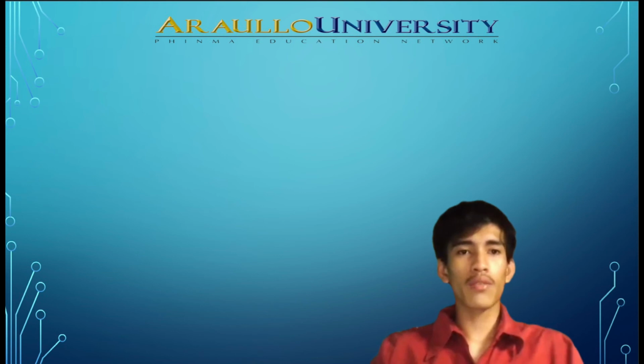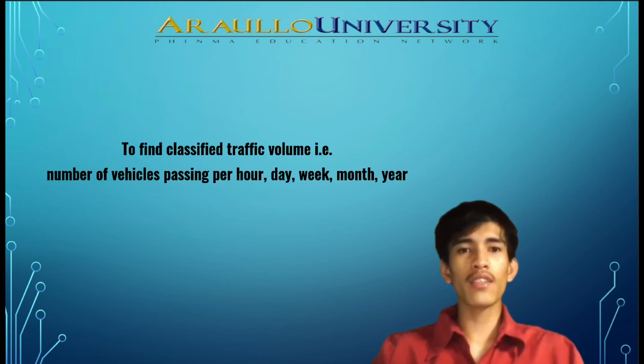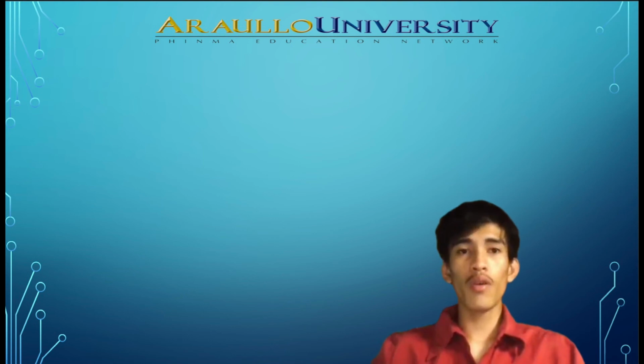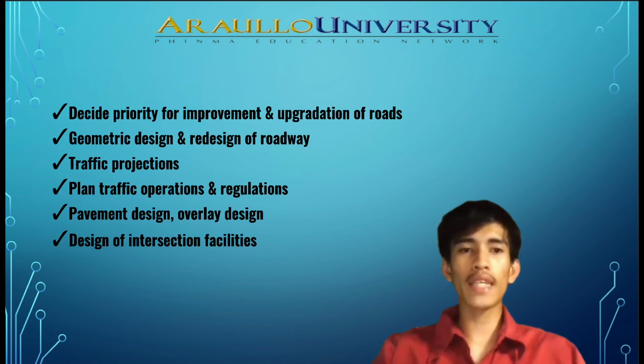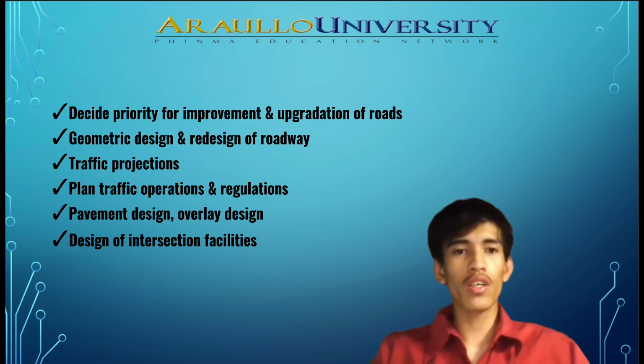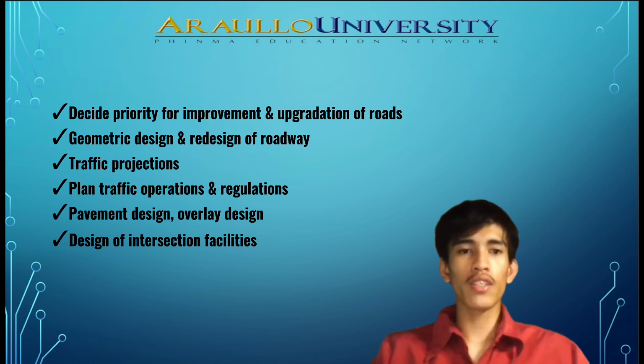Traffic volume studies. Why? To find classified traffic volume, number of vehicles passing per hour, day, week, month, and year. How? Manual count, videography, automatic traffic counters, classifiers. Uses: decide priority for improvement and upgradation of roads, geometric designs and redesigns of roadway, traffic projections, plan traffic operations and regulations, pavement designs, overlay designs, design of intersection facilities.